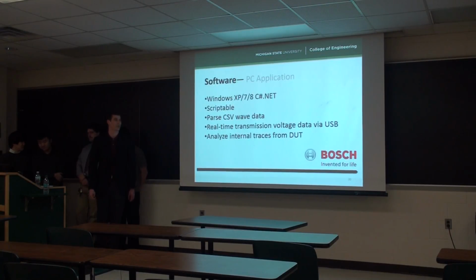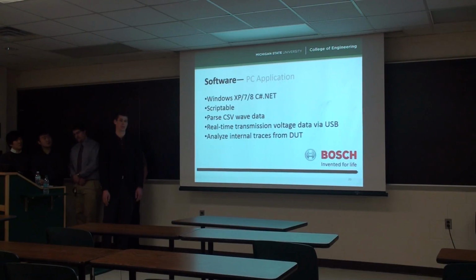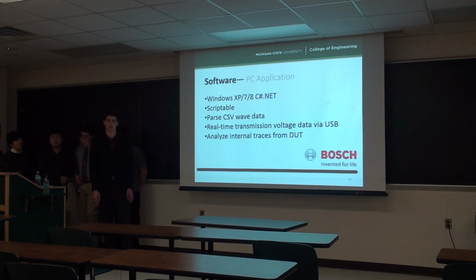So the PC application, according to Bosch specifications, will be written in C#.NET using the Microsoft Visual Studio toolchain. And it needs to be scriptable so that Bosch engineers can load up profiles and determine how many times those profiles are going to run, also, and however many different profiles that they want to run as well. So basically it's going to be able to parse CSV wave data, which is just going to be voltage versus time metrics. And the PC application is going to send that information in real time over USB because the available on-chip memory of the microcontroller is not large enough to handle all the data within the CSV.